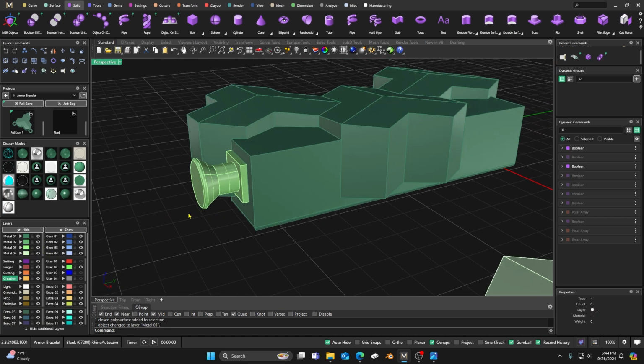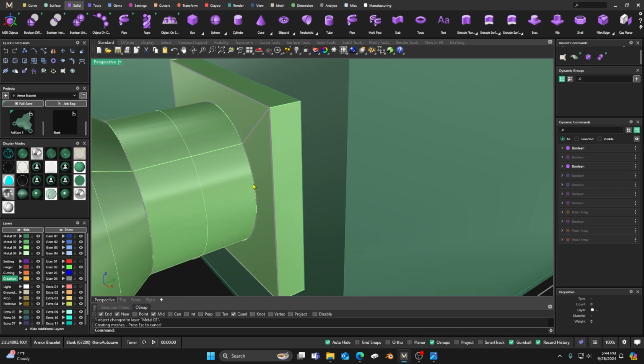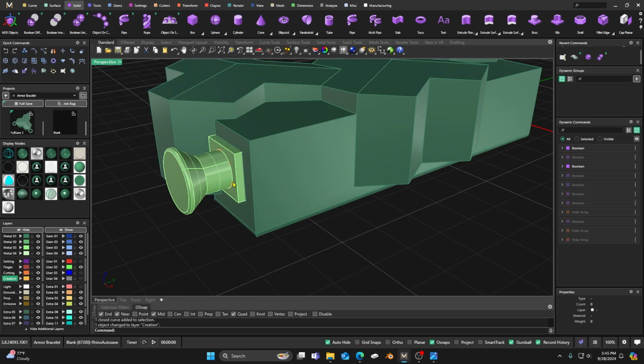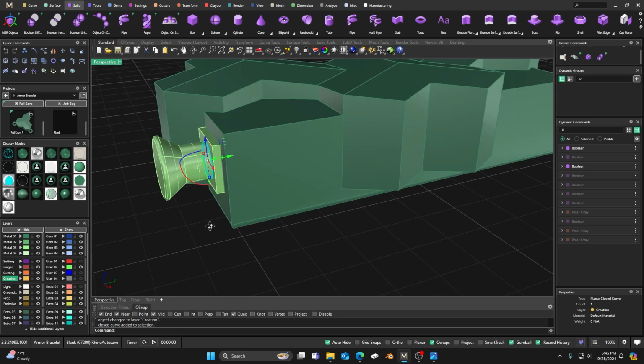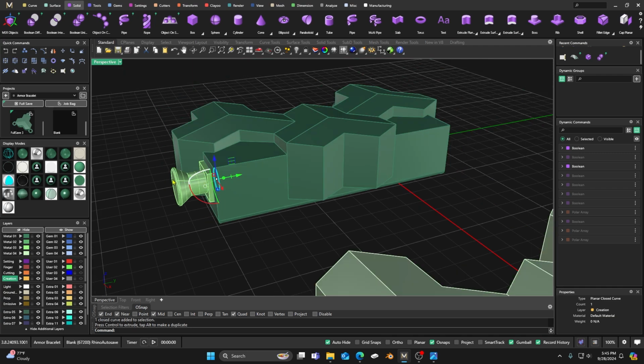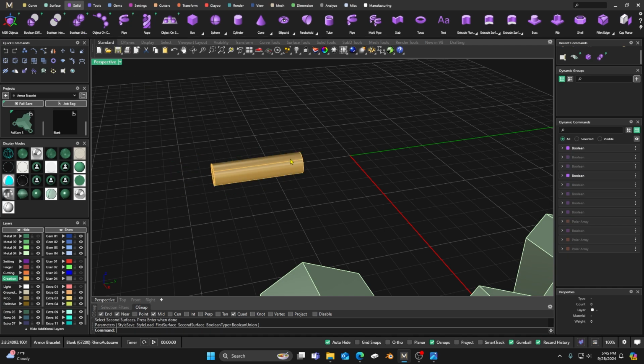All right. Next thing I'll do, I'm going to bring back the gray because there's a bunch of gray that we have out there, but I only want to grab this one right there, right? Okay, and I'll change that one back to yellow, and then I'll just go ahead and hide the rest of that gray, and then I'm just going to take this one and drag it in a little bit, and I'm going to turn off my green, and then I'll just extrude it, something like that, right? And now I can go to Boolean Union, enter and enter and enter.